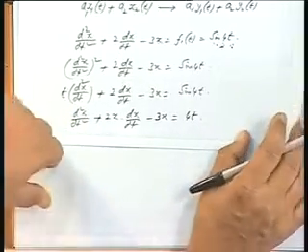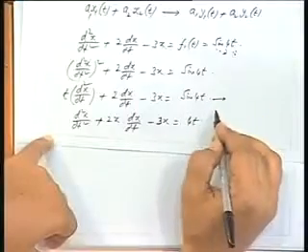So you must be in a position to identify a linear system from a nonlinear system. This is also a linear system, but it is having a time varying coefficient. A very nice example of a linear time varying system will be, say, a furnace. You have the brick lining. If you start an experiment now with so much input of fuel, say, so much charge kept, and you perform the experiment today and tomorrow, there is not much of a change in the furnace characteristics. So if you write the heat flow equation, you will find the equations are identical.